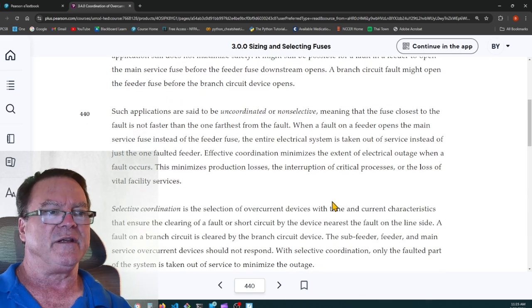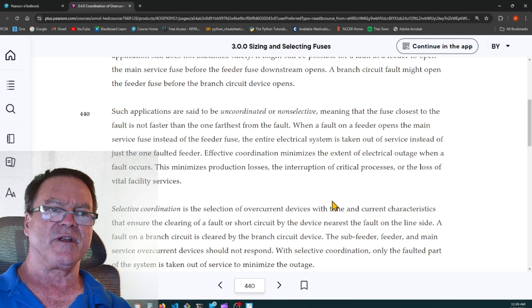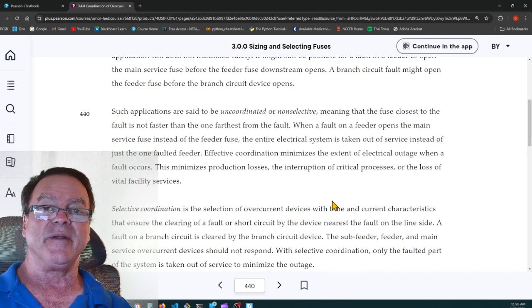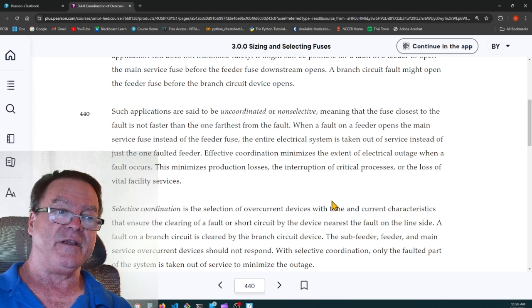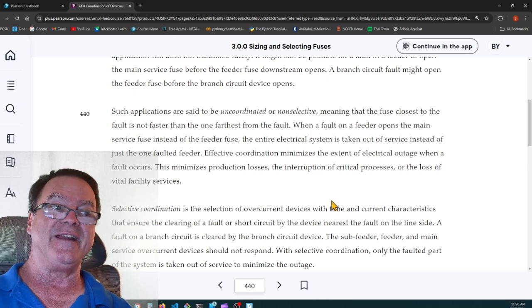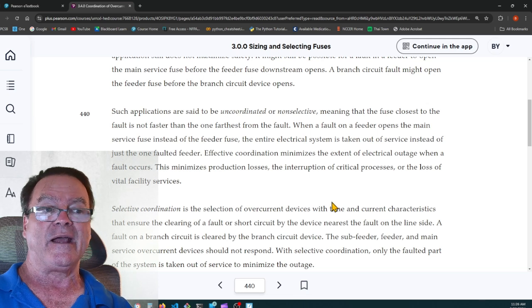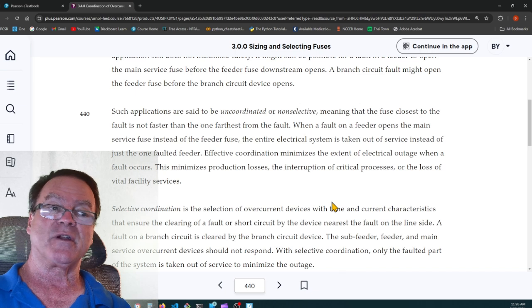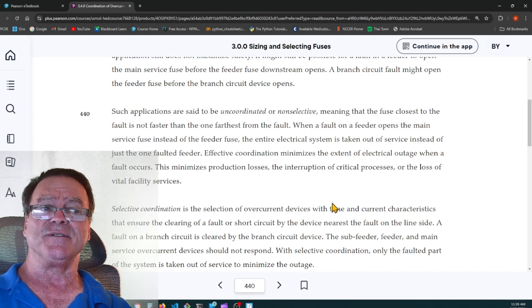So basically, you want to have the branch circuits at current limiting, half a cycle, and maybe the main circuit breaker for that panel at 2 cycles. And the circuit breaker in the main panel feeding that sub panel might have a delay of 3 cycles, and the main 1,000 amp circuit breaker in that main panel might have a delay of 6 cycles.